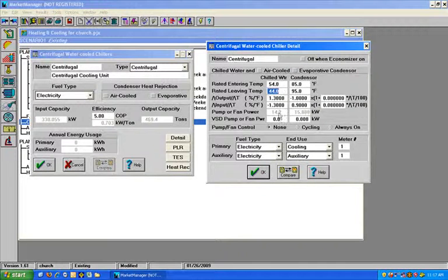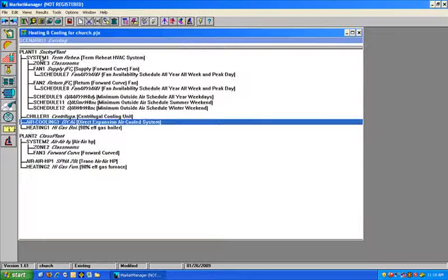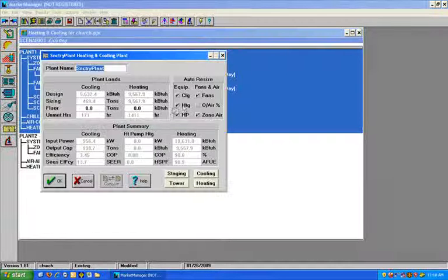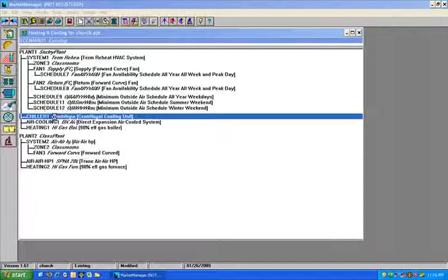And then this is your pump power. This is your chill water pump, or all your chill water pumps together. And this is your condenser water pumps. If you've got an air-cooled chiller, then this would be your condenser fans. Okay. If you've got, here, let me quit auto-sizing the cooling equipment and go back to the chiller.